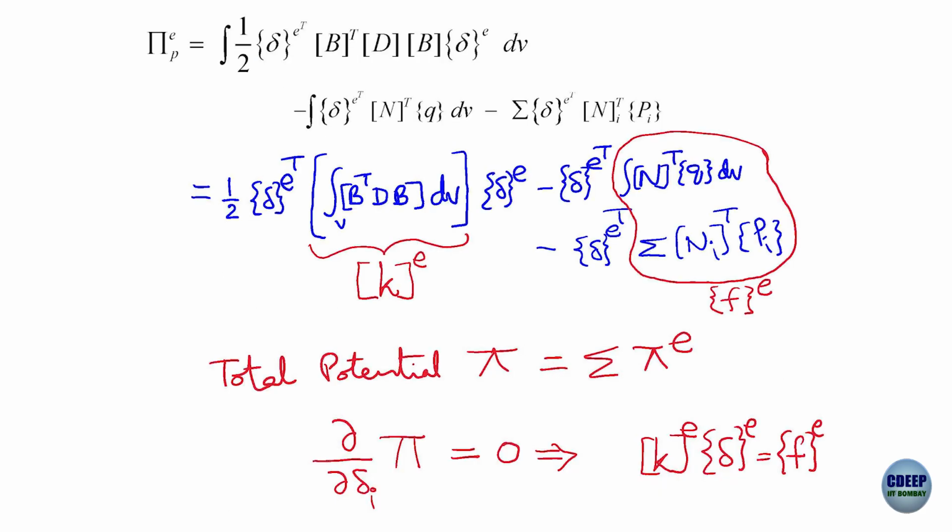So, we have the total potential for all the elements, and then the variation, perturbations in the total potential expression, are obtained by changing the nodal values of displacements u1, v1, u2, v2, u3, v3 all over the structure. So, if this has to be a minimum for equilibrium, then its partial derivative with respect to u1, u2, v1, v2 etc., has to be 0.